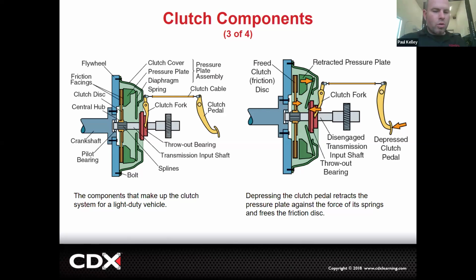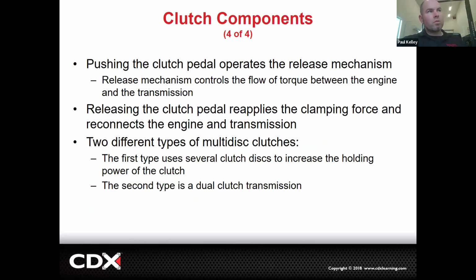Did this transmission go low on fluid? Is it possible that there are other problems inside the transmission? So a lot of shops would say if it's a transmission input shaft bearing, you need to rebuild that manual transmission. All right, so there's some really good diagnosis you can do just from a road test. All right, and that's kind of what this is talking about.